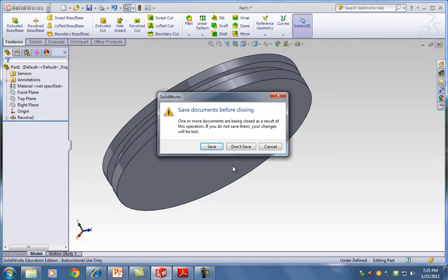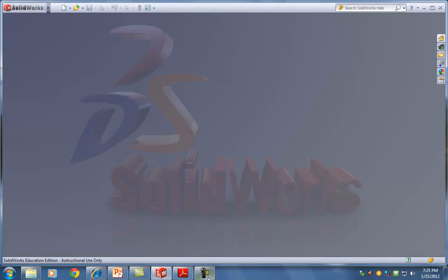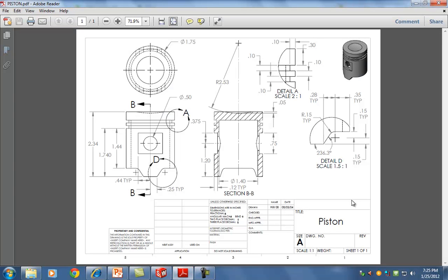All right, so now what we need to do is figure out how to do the same thing for the piston. One of the things we should notice about the piston is it's actually empty from the inside. So instead of doing the profile as the entire thing, what if I just do the thickness of the piston and leave the inside empty, so when I revolve it, just like I did with the mug, I end up with an empty inside, instead of going to the bottom again, drawing a circle and extrude cut.